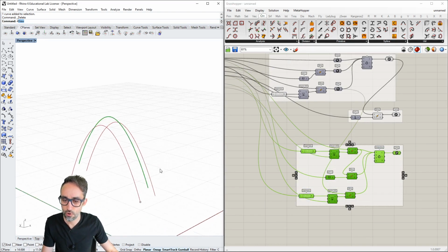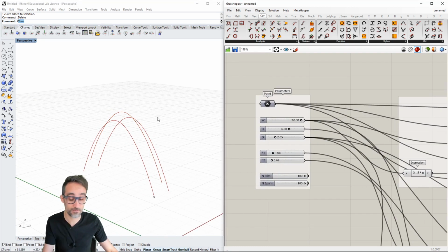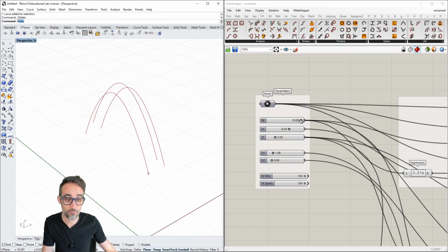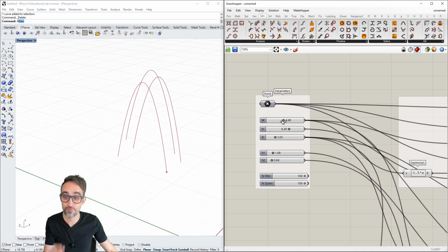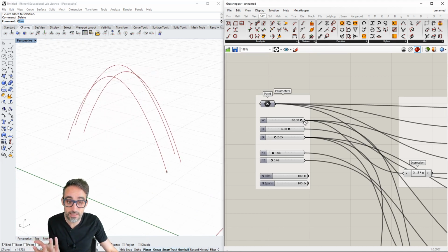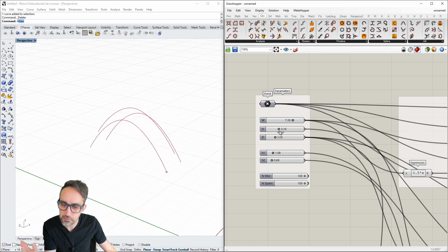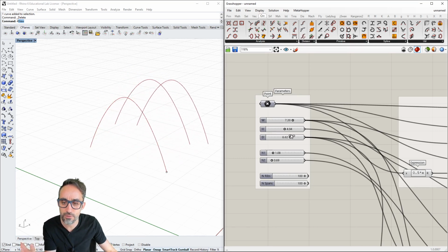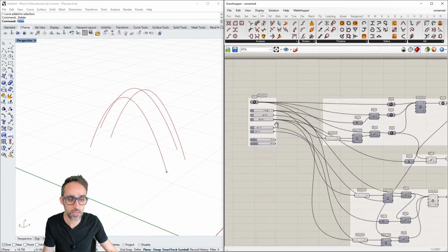All right. So is this parametric enough? Let's see. This is a check that is very useful to do. Let's see if we move the parameters, do things move around in a way that makes sense? So width, everything is changing accordingly. The height, it looks like things are changing accordingly. The depth, things are moving. Nothing is going off. This goes up, this is going up. So it looks like things are pretty tight. I like what I'm seeing here.